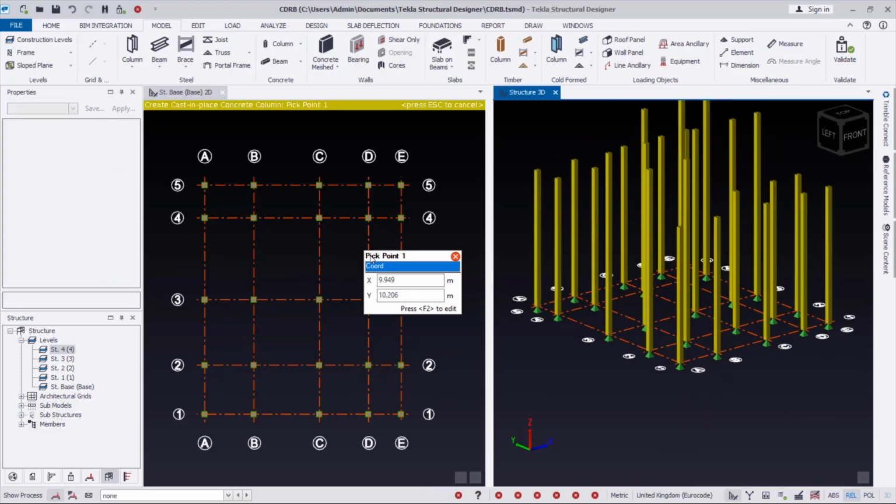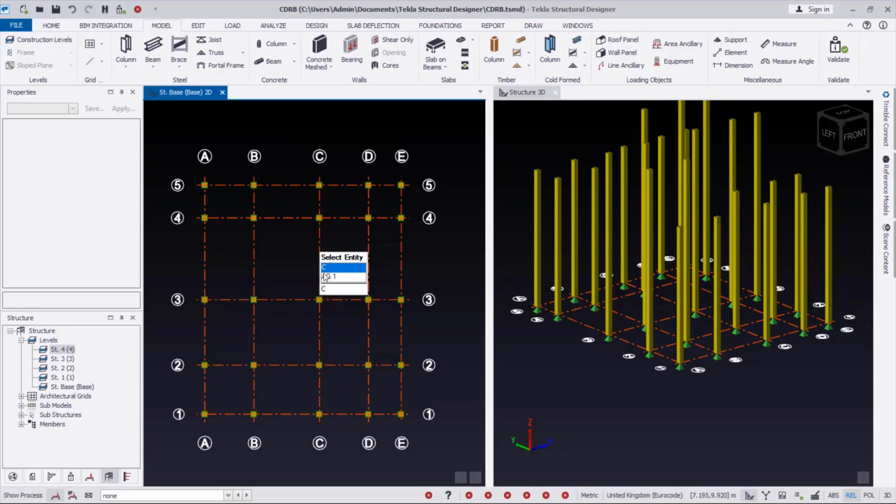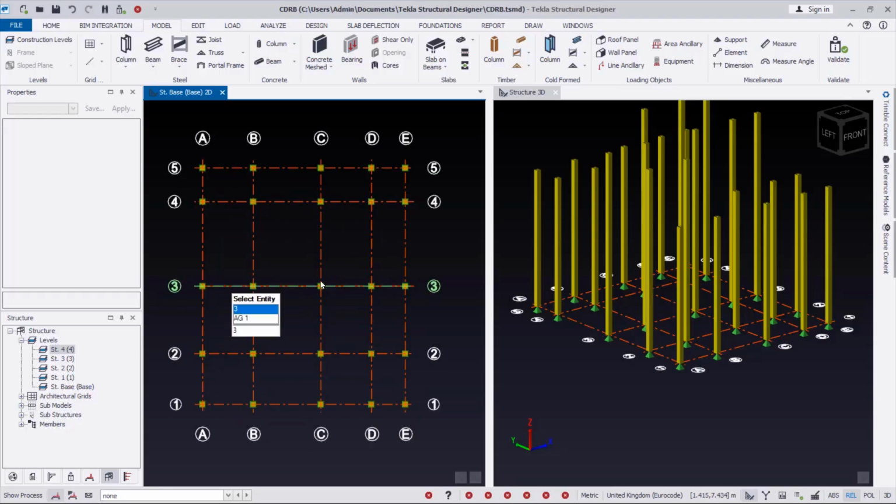Okay. Now the next thing we'll model is the beam, reinforced concrete beam. So you have to escape by using the escape key. Each time you finish with any command, use the escape key on the keyboard to actually escape that command successfully before you commence another command. All right. So being on this window, we click on the beam right here.